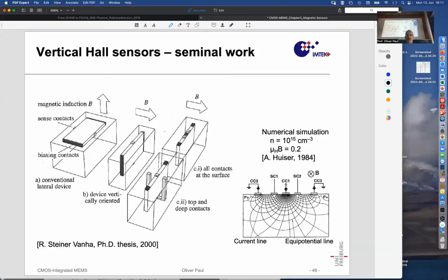If I follow this space between lines, I end up at another location, so these must have a voltage difference between them due to a magnetic field, as indicated. And in this case, it would rather look like what we have seen with the long Hall plate, with, however, slightly offset sense contacts on the surface.